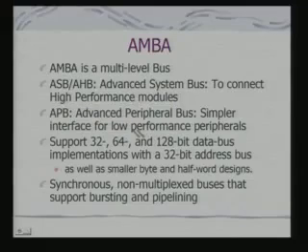So again, as we have seen, it's a multi-level bus. At the system level, the bus is called ASB or AHB. These are two different bus specifications and they have different capabilities. They define the structure of the system bus. We shall not really distinguish between them. We shall look at their characteristics more in reference to AHB, and these parts will translate in most of the cases to ASB as well.